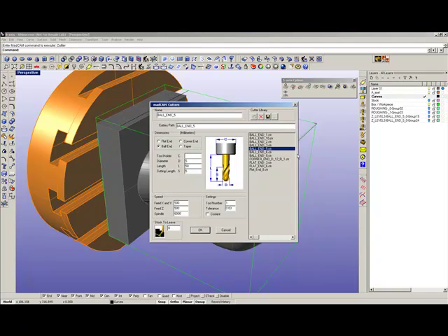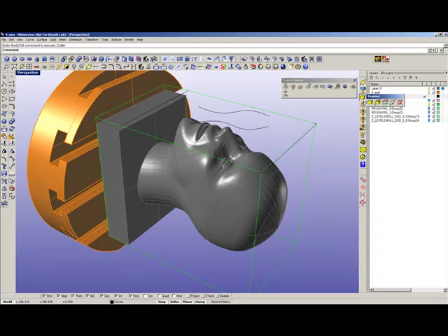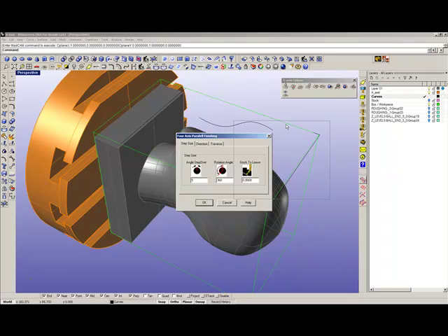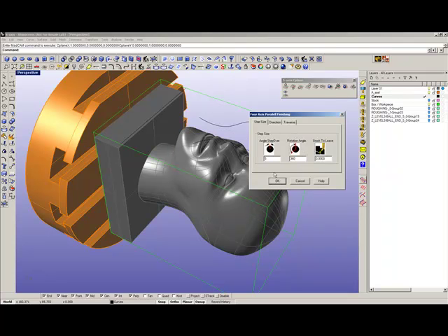First we select a 5mm ball end cutter, and we select a region, 4-axis parallel finishing, and this will rotate the A-axis and go back and forth along the X-axis, and we can set the step over, and if we set 5 degrees and rotation angles 360 degrees is all the way around the model, and we can